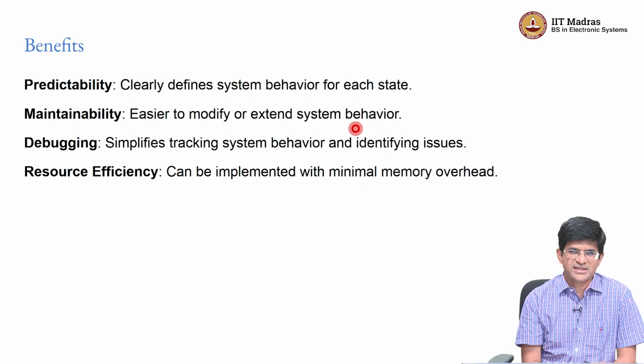Now, in an embedded system, you probably don't care to minimize it that much, but what it means is that even with, let's say, just an 8-bit number to represent a state, you could have potentially up to 256 different states. And usually you don't want to go for such large designs or large state machines for other reasons. But what that means is that the state definition and keeping track of it is by itself not going to require a huge amount of resources.